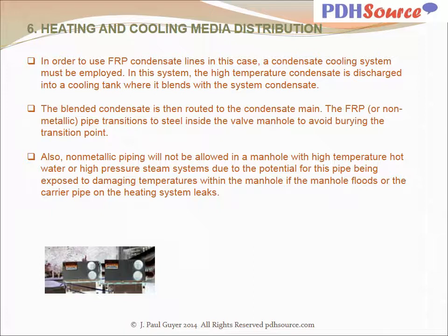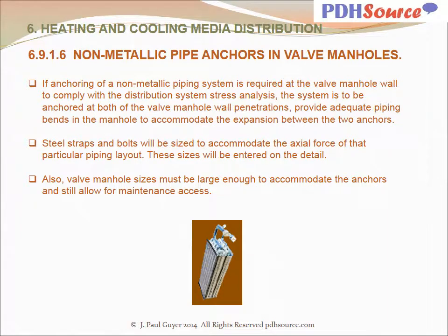Also, non-metallic piping will not be allowed in a manhole with high temperature hot water or high pressure steam systems, due to the potential for this pipe being exposed to damaging temperatures within the manhole if the manhole floods or the carrier pipe on the heating system breaks or leaks.